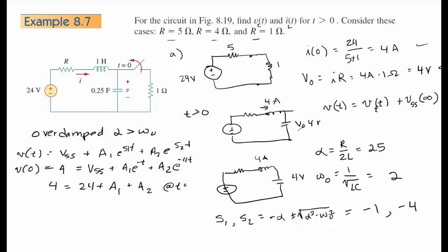So a moment of confusion there is that it is at t equals 0, because I thought, oh, that's V steady state at t equals infinity, which would make this term go away. But that's not true, because we know that the solution that we're looking for is the transient plus the steady state. And so we have to find the steady state, and we know it's 24 volts, and we know the solution will have this form where the steady state response is part of the solution together with the transient response, and that will describe the whole solution.